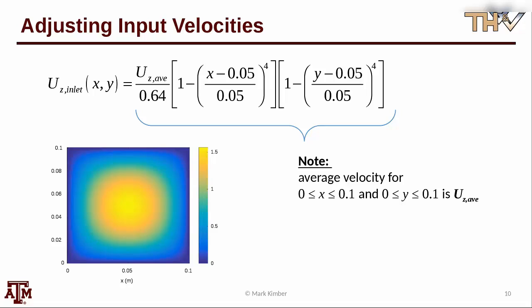In reality, if we're comparing to experimental data, then hopefully we have velocity measurements, we have turbulent kinetic energy measurements, we have a way to estimate dissipation profiles. And so these inlet quantities are very rarely going to be a single number. So how do we account for the fact that it's a profile as opposed to some uniform profile?